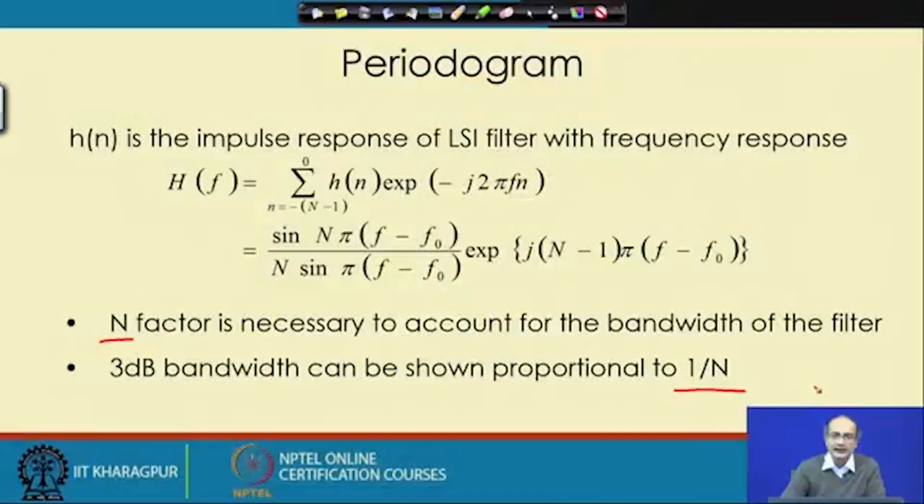As we have more and more data, it will go towards the ideal condition, where the band pass filter collapses towards a delta function and gives us the exact energy at that particular frequency. So, it is moving towards ideality. That is the second result we get, and that gives us much hope about the periodogram.